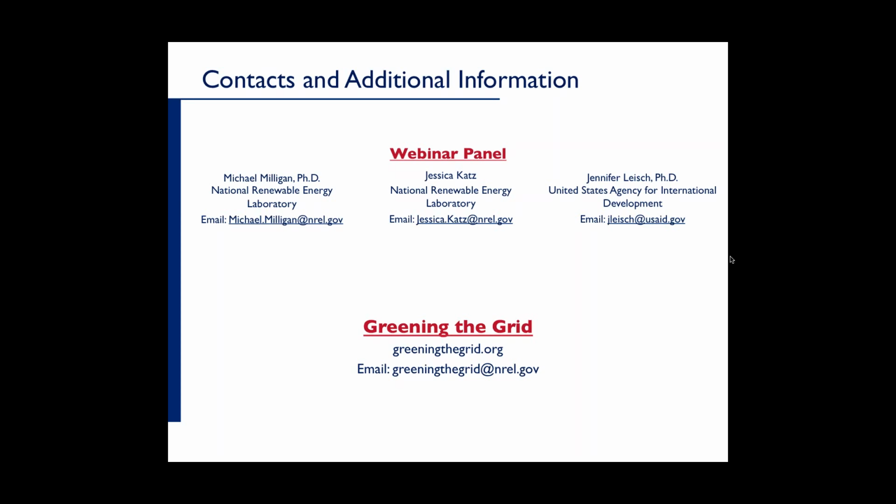Well, that's a good question. I suspect that there's not a one-size-fits-all answer, but I think markets themselves aren't necessary to achieve the things that we know will help with renewable integration. There are two factors that I talked about in the presentation that help a lot, and one of those, if you recall, is enlarging the size of the balancing area, and the second one is to go to a faster economic dispatch, going to 5-minute or sub-hourly dispatch. Both of those can be done with a market, but it's not necessary that you have a market.